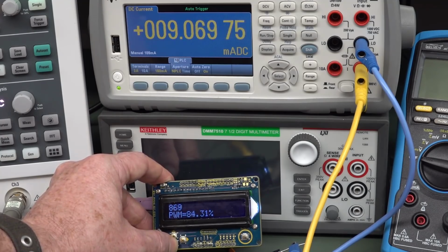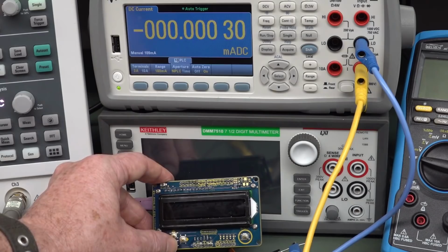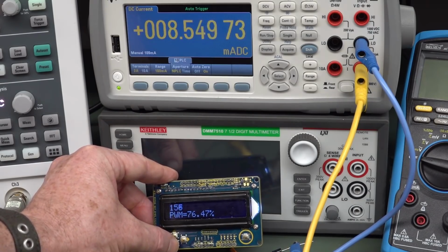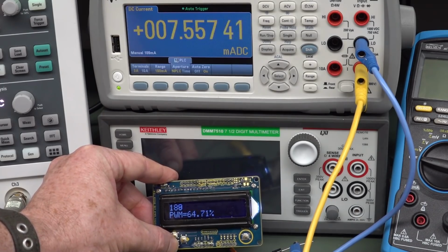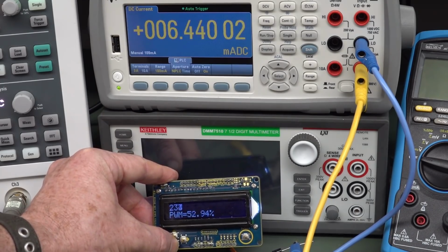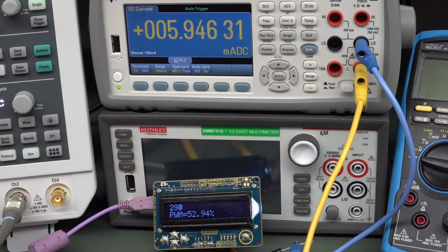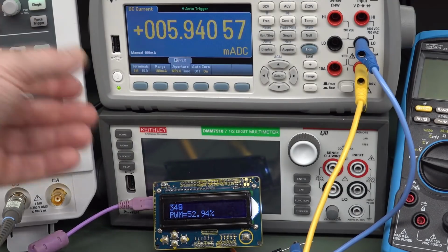The internal diffusion capacitance is making its way back out. Internally, it's going to be significantly different to what we see externally on the scope. But look at this, it's still working and we're lowering the consumption. Yeah, it's fairly linear. Look at that. So we've halved our consumption by PWM at 50%. But it depends on how much diffusion capacitance you've got in there, what voltage you're operating at, what temperature you're operating at, all that sort of jazz.